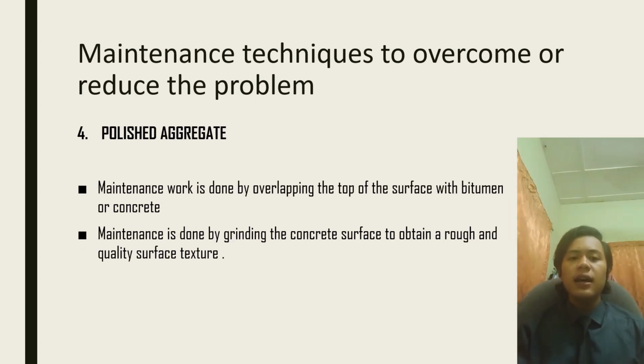Okay, next, maintenance techniques to overcome or reduce the problem of polished aggregate. Okay, firstly, maintenance work is done by overlaying the top of the surface with bitumen or concrete. Okay, lastly, maintenance is done by grading the concrete surface to obtain a rough and quality surface texture.